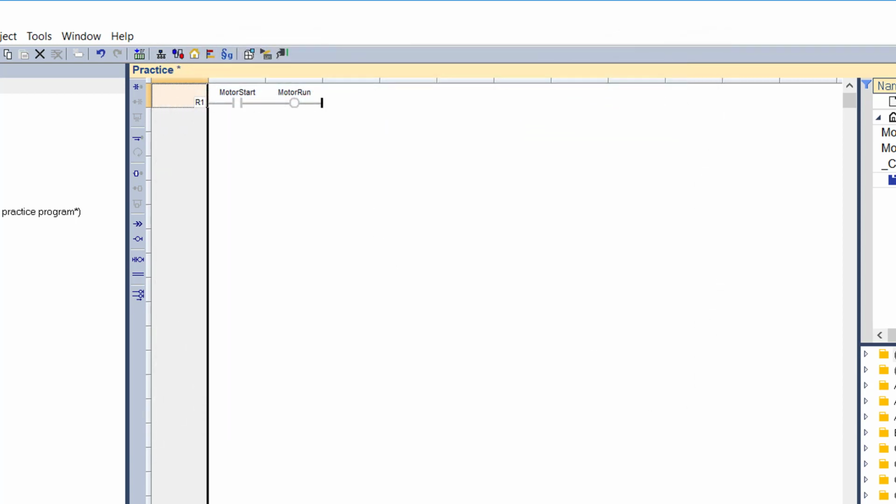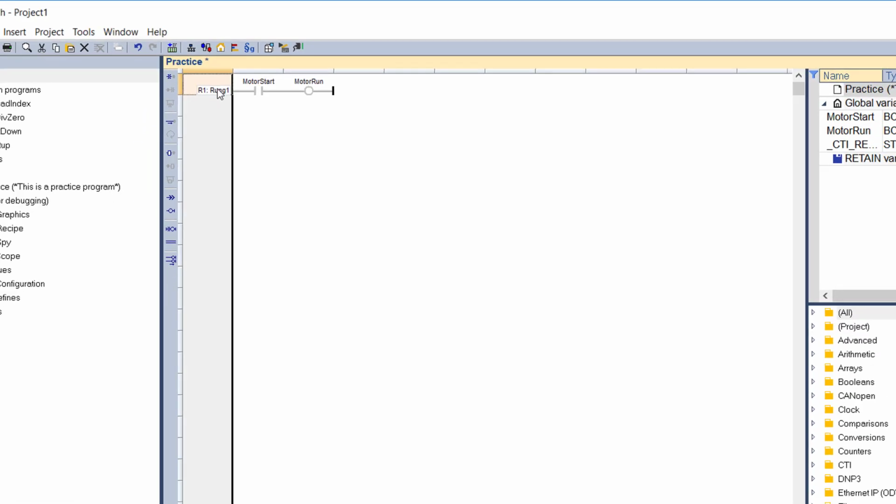Let's see how these components are used to build a ladder diagram. A ladder diagram is a sequential list of rungs. Each rung represents left-to-right Boolean power flow, that begins with a power rail, and finishes with a coil or a jump symbol. Each rung is identified by a default numbered label, displayed on the left of the power rail. The rung label can be used as a target for jump instructions. You can edit the rung label by double-clicking in the rung head, on the left margin. The ladder editor enables you to manipulate whole rungs, by selecting only their head, in the left margin. Once selected, you can use normal cut, copy, and paste operations.